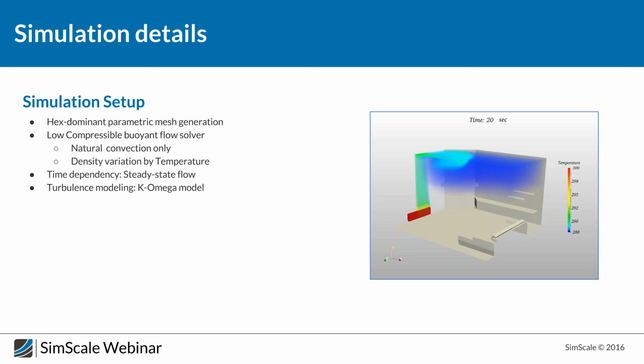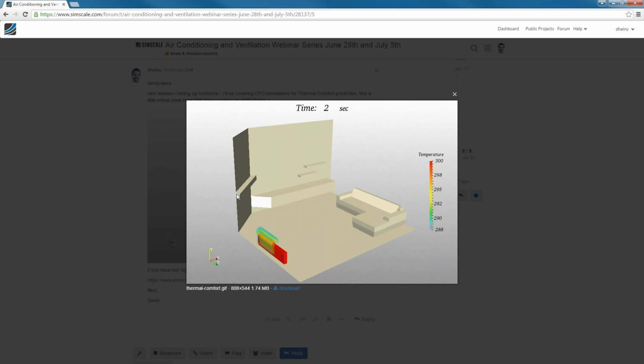It's computationally much more efficient, and this allows you to run many more simulations faster, specifically in early design phases. During the conceptual design, it oftentimes makes no sense to run a very, very detailed transient analysis, because the only thing you want to identify is whether you are on the right track, right? And then you want to run many iterations of it. Here, the steady state analysis gives you a much better tool in these early design phases. Once the design needs to be delivered and you're coming closer to the deadline, then you might want to do a last transient analysis, a dynamic analysis, like the one I just showed, to make sure that also the ramp-up phase is correct, etc. That's the difference between transient and steady state.